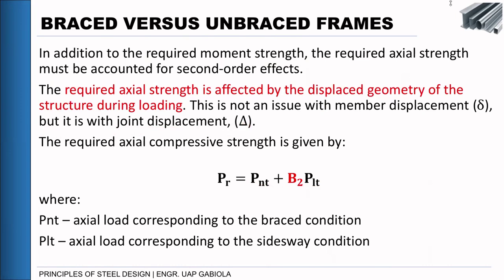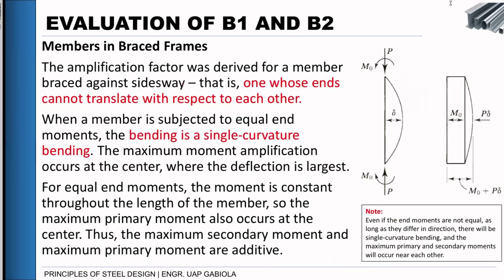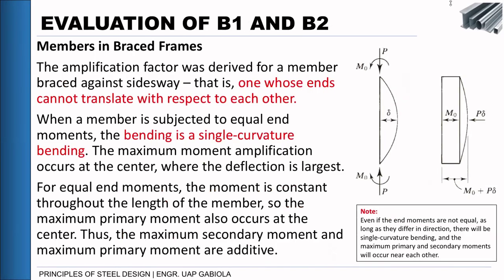But first, we focus only on the braced frame now, members in braced frames. For members in braced frames, the amplification factor was derived for members braced against sideway. Okay? For members whose ends cannot translate with respect to each other. Braced against sideway.